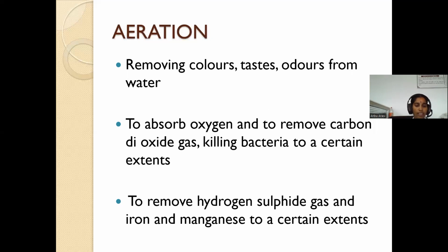Next, excessive manganese content. Manganese levels over 0.5 milligram per liter lead to black to brown discoloration and impart a little metallic taste to water. Heavier exposure over a period of years has been associated with nervous system toxicity, characterized by abnormal movements. Excessive fluoride content.